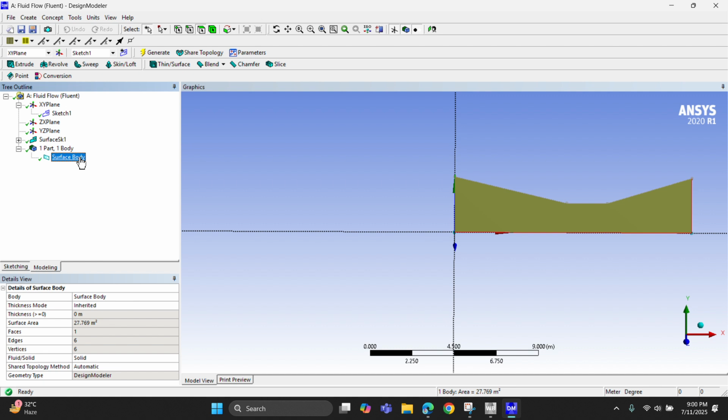When we use the fluid flow model, our full domain is always a fluid domain. Here you see the domain is by default a solid domain, so we change the solid domain into a fluid domain, then generate. Okay, so our domain is a fluid domain, and our geometry looks like this.